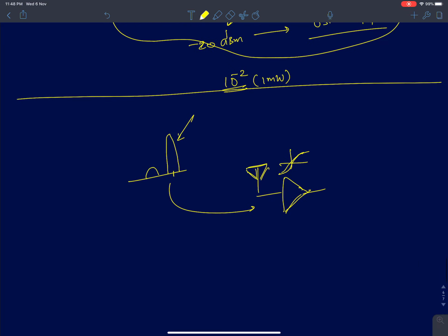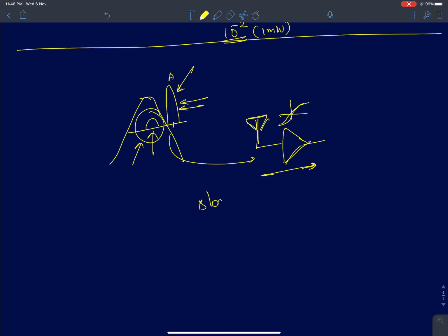And we said that if the amplitude of the unwanted signal is high enough, it can completely desensitize the receiver. It will behave as though it has no gain for the input signal. This is the signal you are supposed to amplify, but your receiver will not be able to do that because of the presence of this interferer. Which is why, as we'll probably see in later lectures, we'll have to introduce filters around the channel of interest, the bandwidth of interest, so that you keep this signal within certain limits. We also use the words blocker and interferer to characterize that this interferes with the reception of the main signal.